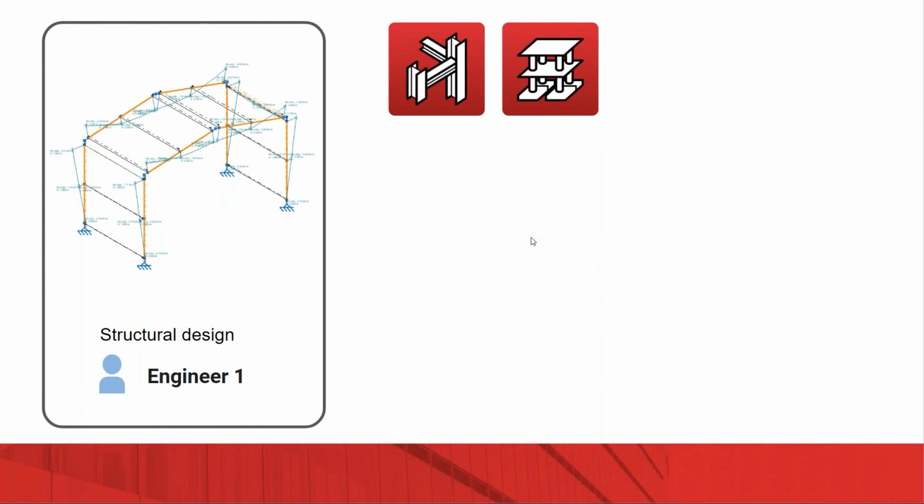In a first step, we will probably have the structural design. So we will define the model of our structure. We will set all the moments, the shears. We will define all the conditions of our structure, analyze according to the wind codes, the seismic codes. We'll have the final sections of each element, the materials that we want.